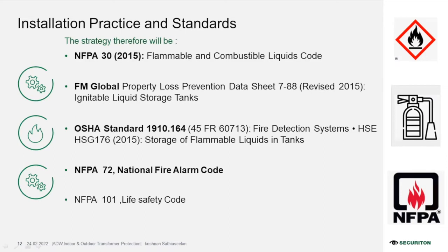Most of these codes and standards explain how you handle flammable and combustible liquids and gases, and they do not narrow down to a detection system. They say you need to look into the fastest detection. So we have to interpret from here and use this as a guideline to determine what the fastest possible detection is for such an incident. A point type detector may not be suitable for such an external, outdoor application. So we have to find the best product that works in such a bizarre environment.